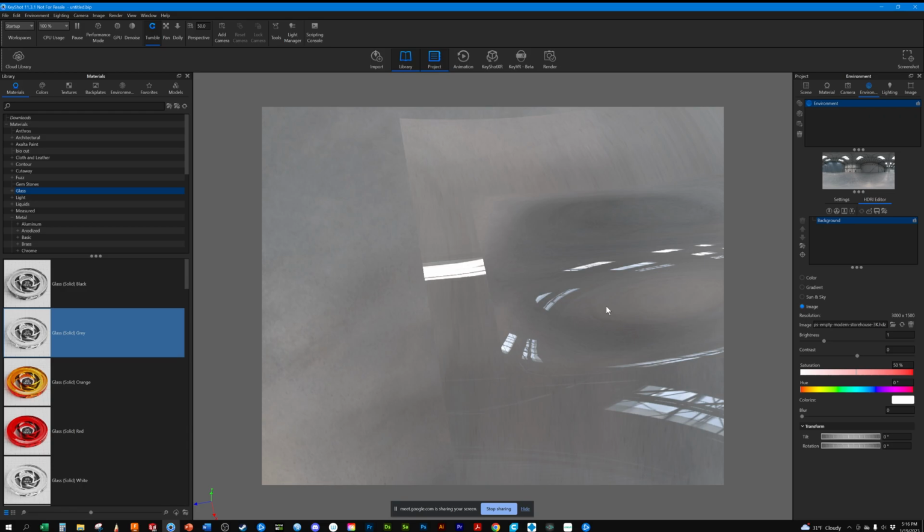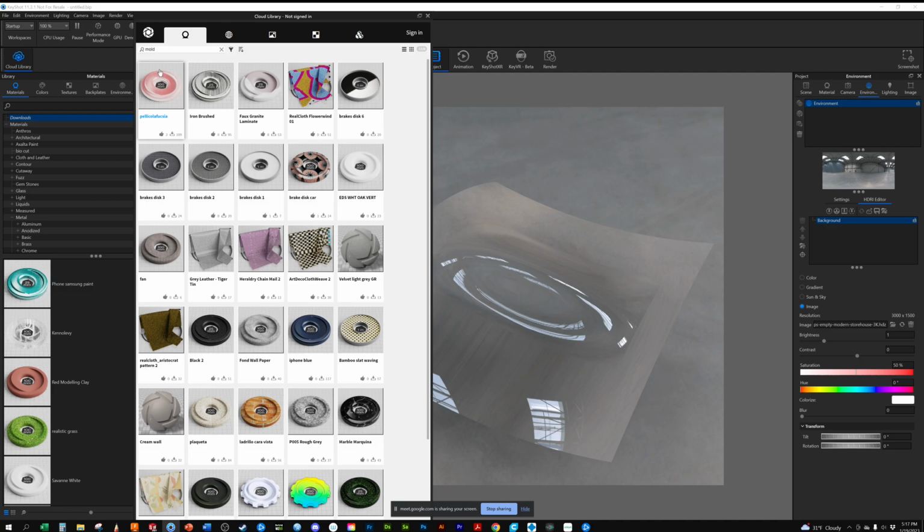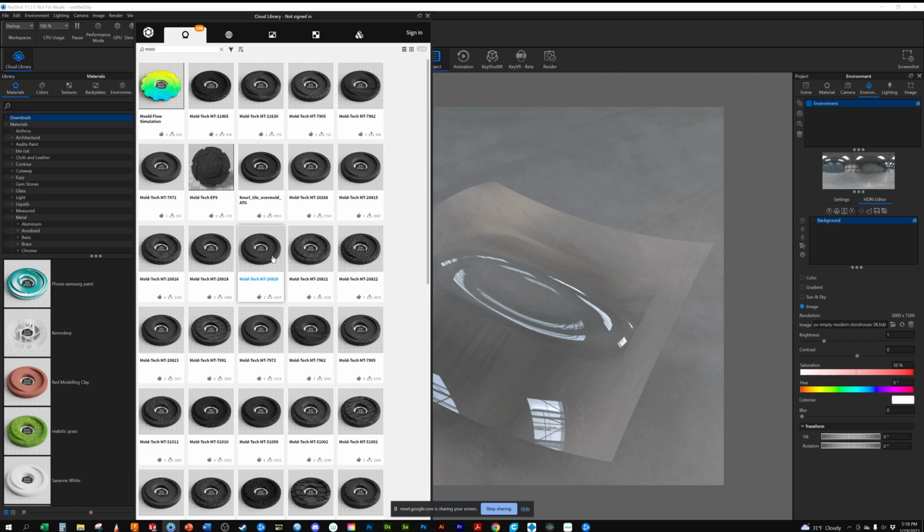So a perfectly smooth Gloss-A surface would be MT Moldtec 1001. There could be a texture that has different coarsenesses. So you can see here, all these are Moldtec textures. You don't have to download them all. But if you look at an electronic component that has a slight texture to it, someone somewhere said this surface needs to be Moldtec MT7962.